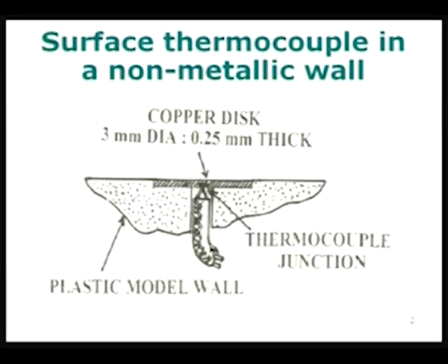In fact, the error in the temperature measured in this particular case can be calculated based on some thermal quantities. We will take it up a little later, and give the appropriate formula. What are the variables which will play an important role? The surface area of the copper disc will play an important role, and the larger the surface area of the copper disc, the better is the heat transfer from the fluid to the copper disc, and therefore you can reduce the error by having a large copper disc here and by using very thin wires for the thermocouple which is attached to the bottom.